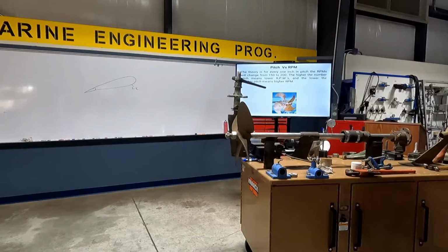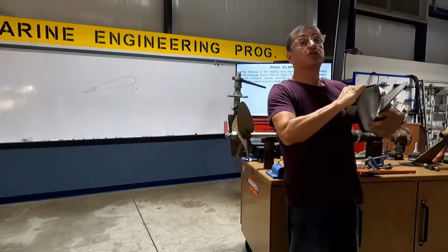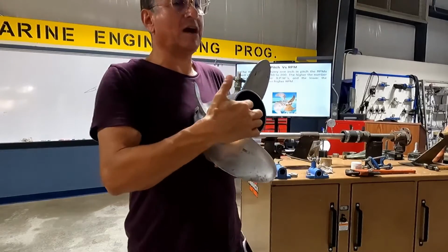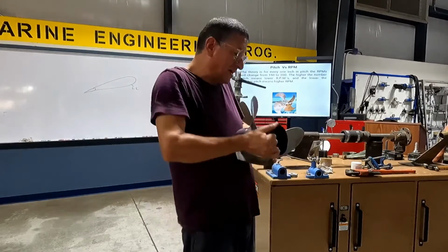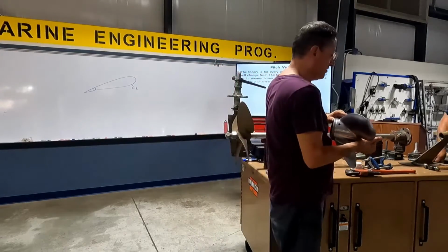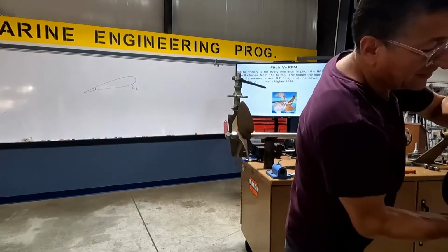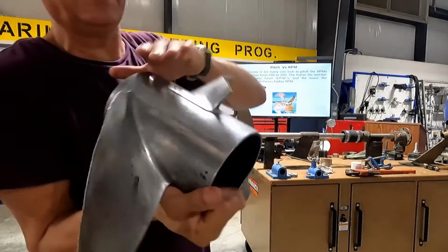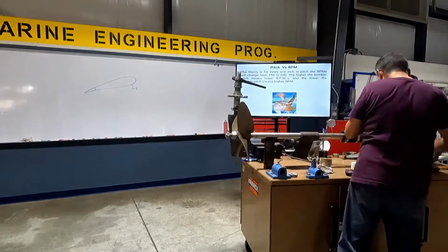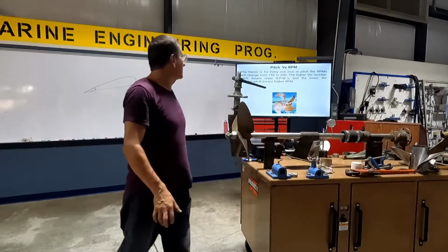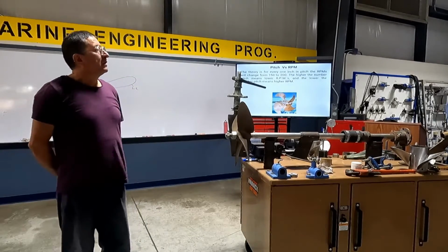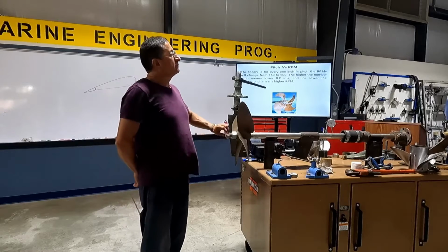You're getting old. You gotta get your glasses on. No, excuse me, 20 in pitch and 14 and a half in diameter, here in the hub. And here is stamped the rake angle, Danny. Some have this, 18 degrees, the rake angle. They say rake angle over there, rake angle over there, 18 on the surface of the propeller. Nice, no? That's the nomenclature in an outboard propeller. The propeller is just as important, because having the right prop makes the difference.